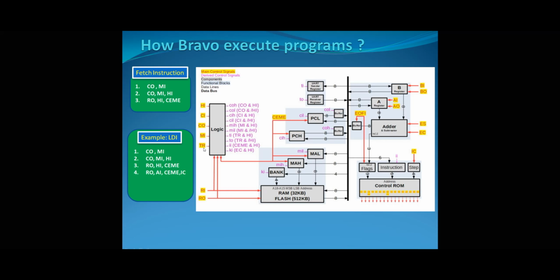So as you can see, by combining the TR again with HI and inverted HI, we actually come up with 2 signals. One will be controlling the RX module, and the other one will be controlling the TX module. So that means that at each point of time, whether we want to send or receive the data, we are actually just outputting the TR signal from control logic. However, depending on the condition of the HI signal, we are either receiving or sending the data.